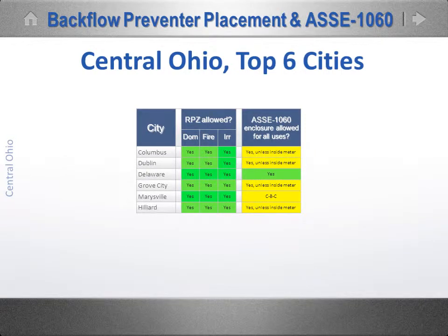If I've been able to persuade you that the coming best practice for containment backflow prevention is RPZs all the time, then there are only two questions to deal with regarding the jurisdiction you're working in. First, are RPZs allowed in any situation where you, the designer, deem it appropriate? And the answer is uniformly yes. Anytime you specify an RPZ, these local water districts are happy to accommodate you. After all, RPZ protection is superior to double check protection.